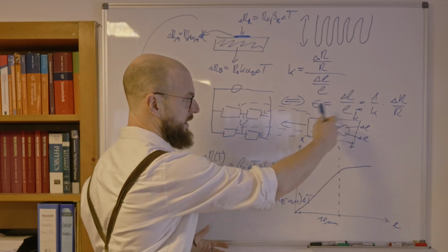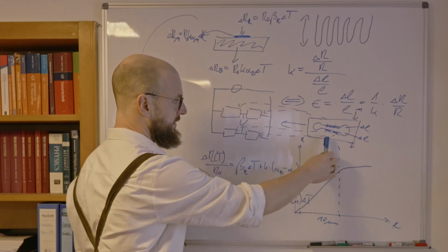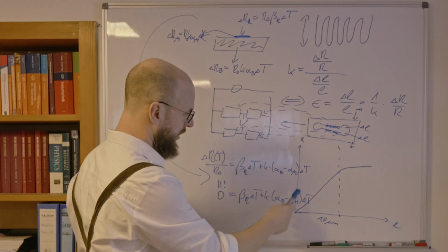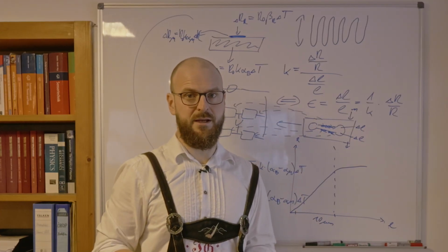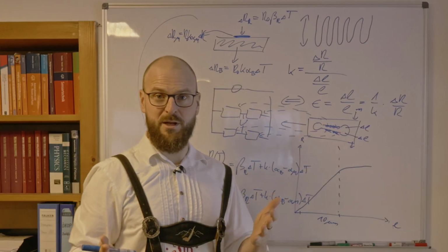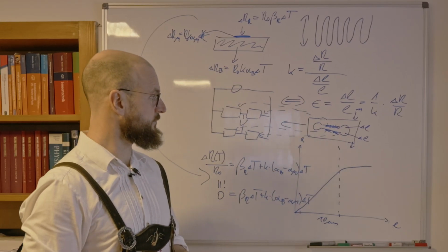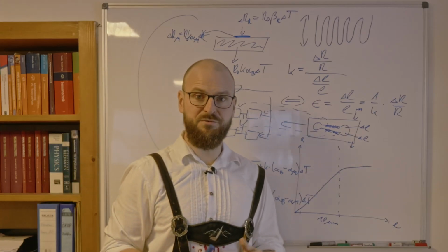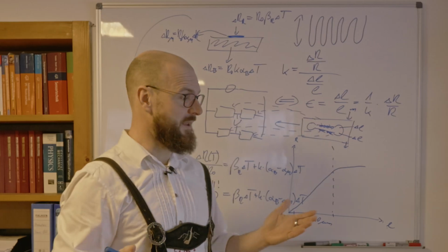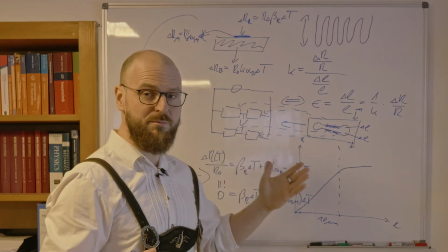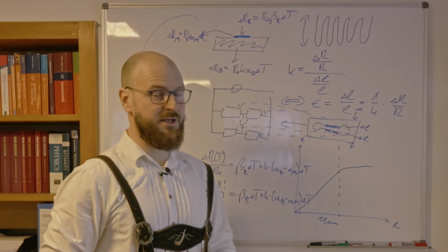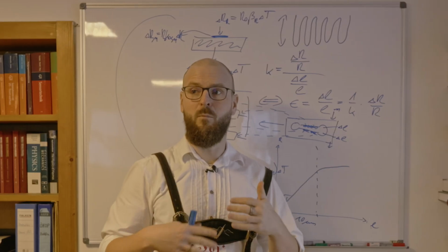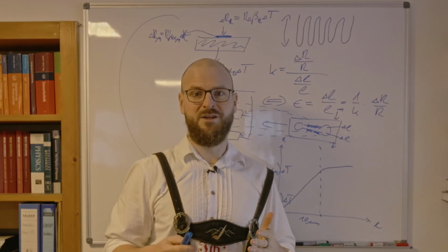And for example, for that weight measurement application, for sure, meaning we choose a material over here, which compensates for the electrical change due to the temperature in the strain gauge. And we have some measurement weighting device, which would be temperature independent. And that's a usable, a good property of those strain gauges also, having some more possibilities to deal with temperature changes and temperature influences.